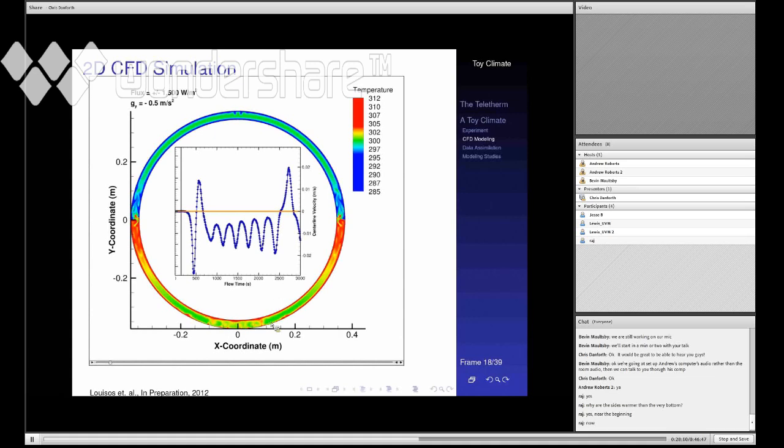But he's saying that over here, the temperature is much warmer in the middle than it is, let's say, down here. So my answer is going to be kind of off the cuff, but my guess is that the fluid down here is not mixing very much because there's nowhere for it to go vertically. Hot stuff wants to rise, and there's really nowhere for this hot stuff to rise down here at the bottom. This is like a little mini Rayleigh-Bénard cell right down here. So the geometry forces it to sit there and not really mix.